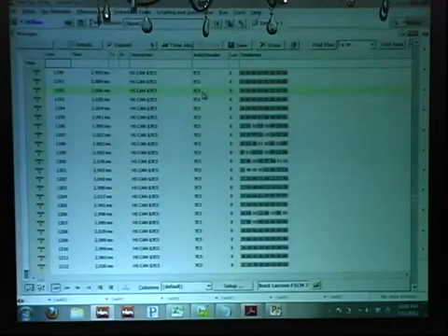If we compare this to Ethernet or anything like that, these messages are very simple, very concise, and the idea is we're trying to have very short messages that live very quickly, but with enough data contained inside of these messages that it can do whatever it needs to do. Like, okay, the temperature of the engine is this. Boom, done. Just 2 bytes of data, 1 byte of data. That's all you need. Now everybody on the network has that information. We can move on to the next thing.